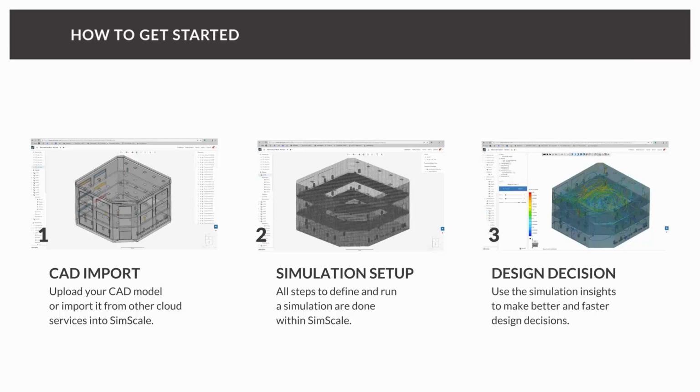And once you've uploaded your CAD model, the first step is what we call meshing. It's actually about dividing one big volume into a lot of small cells. And later we will only calculate velocity and pressure for the center of each subvolume. So in the end, you're dictating with your mesh the local accuracy of your simulation.